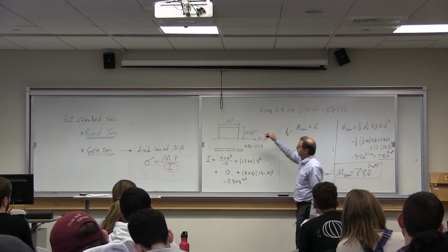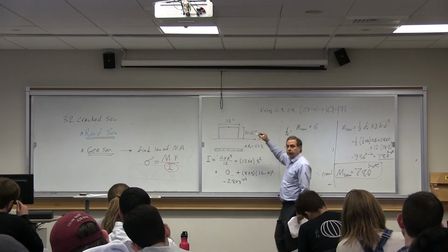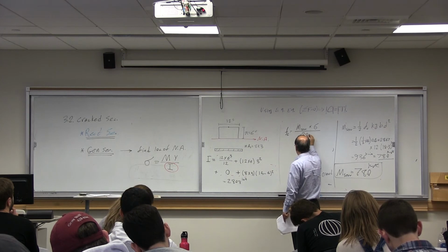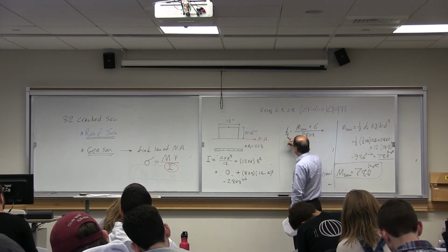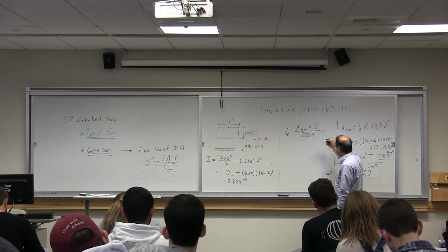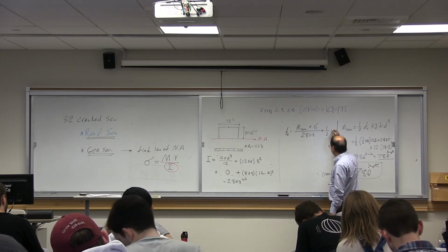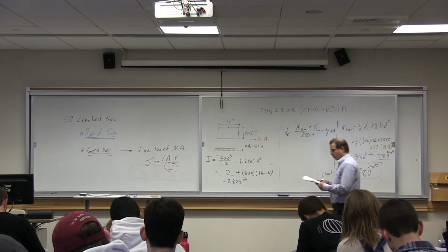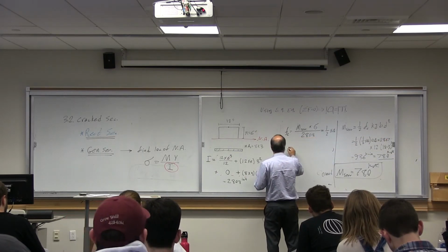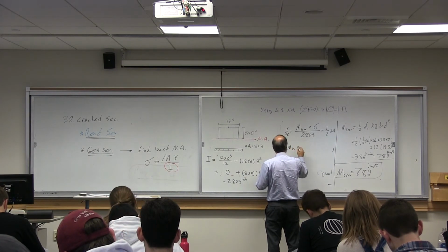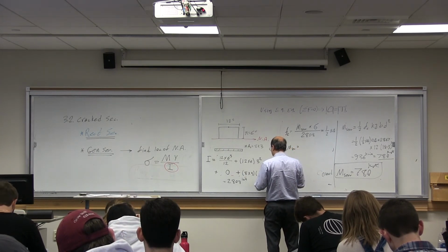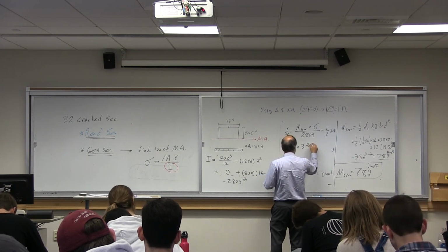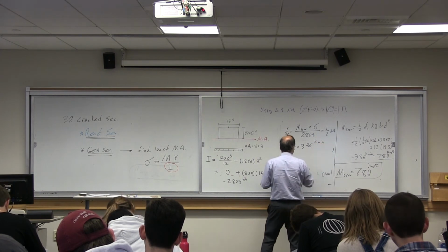Here is stress at the very top, divided by 2808, equal to Fc is equal to 1/2 of F prime c, is equal to 1/2 of 4. From here, if you calculate M service, you will get same number as before, which is 936 kip inches.